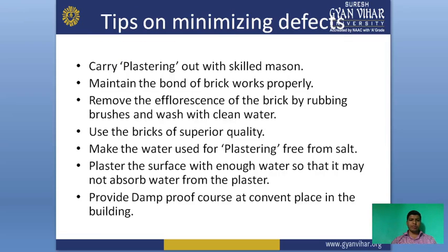These are some tips to minimize or avoid the defects. First one is we have to carry out the plastering with a skilled mason. We have to use a skilled mason for plastering. Maintain the bond of brickwork properly. We should maintain the bond of brick properly, like in a straight line. There are also header and stretcher.